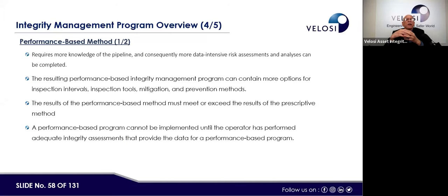Performance means we specify certain KPIs. Let's say if the effluent assessment result shows any presence of SRBs, then we will be injecting biocide treatment into the pipeline. Or similarly, if there is a high level of oxygen corrosion, then in addition to mechanical scavenging, we will also do some oxygen chemical treatment to remove oxygen from the water. Similarly, if there is a hydrocarbon line and the weight loss coupon indicates some metal loss, then we will be doing inhibition and so on.